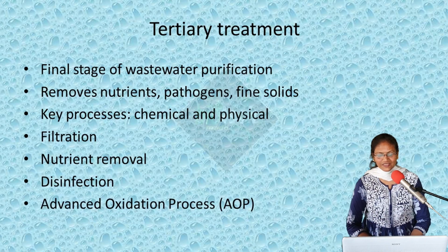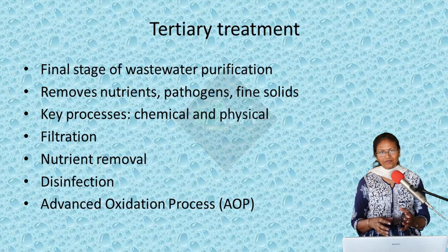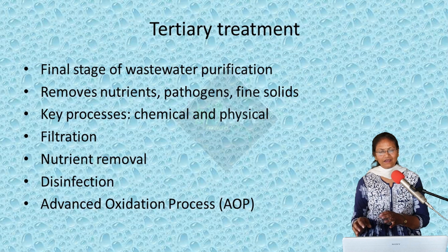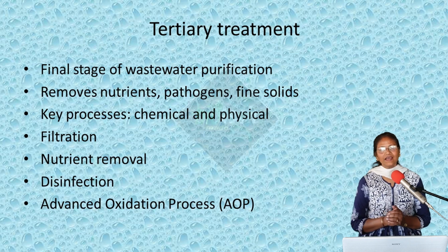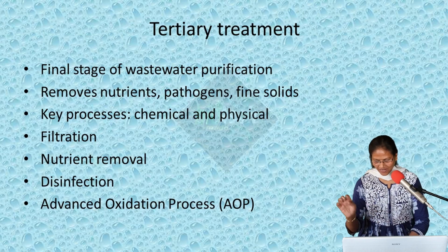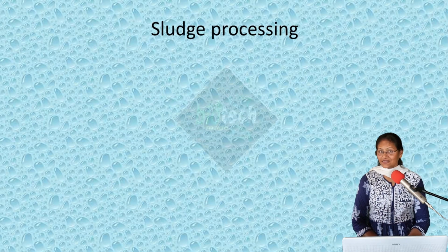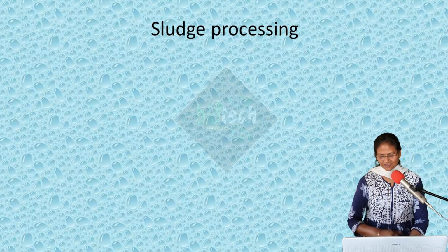And then we use the advanced oxidation process. Here very reactive hydroxyl ions are generated, and they can degrade all kinds of pharmaceuticals and dyes and microplastics, whatsoever is there. Then the next is sludge processing.